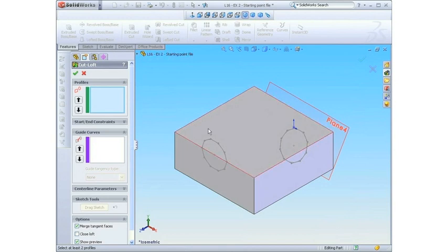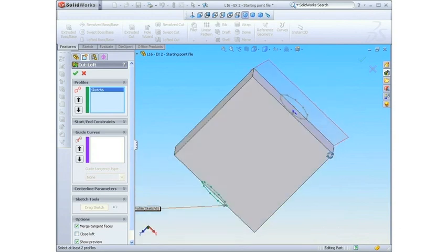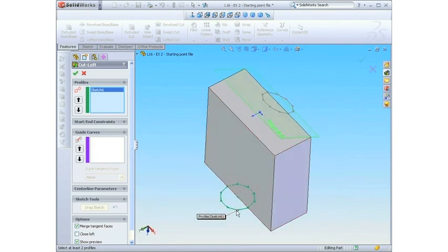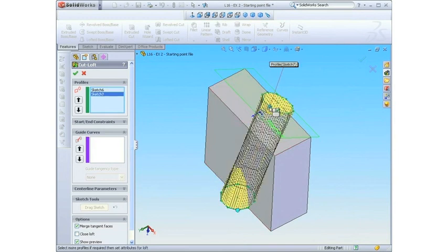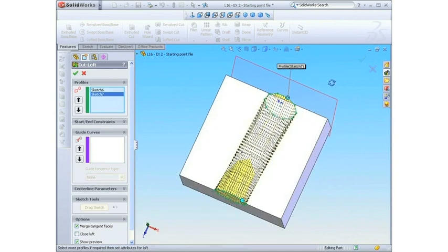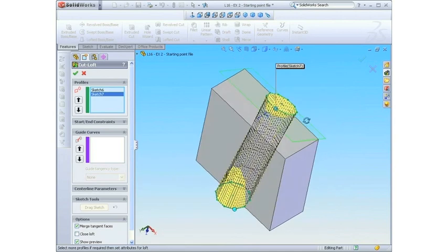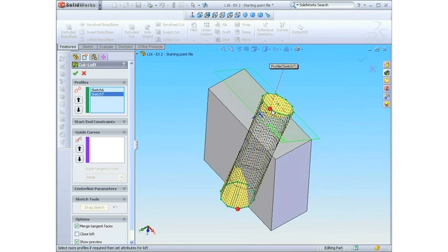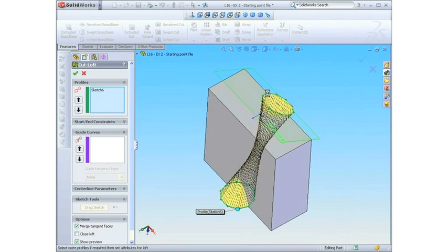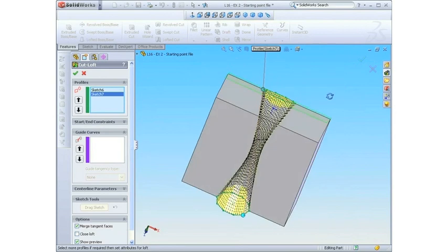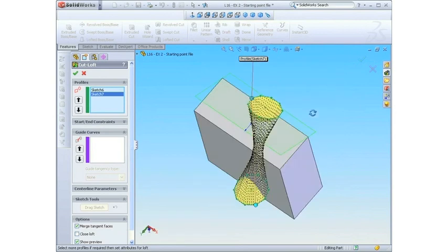With the lofted cut selected, we can select our first profile. And in this case, we've got multiple edges around our profile. So depending on where we select our second profile is going to define the rotation of that profile. I'm going to unselect where I selected this profile and select farther over here. We can now see that I've got quite the twist to my profile.